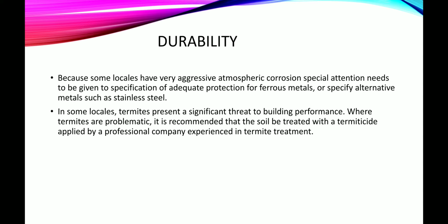In some locales, termites present a significant threat to building performance. Where termites are problematic, it is recommended that the soil be treated with a termiticide applied by a professional company experienced in termite treatment.